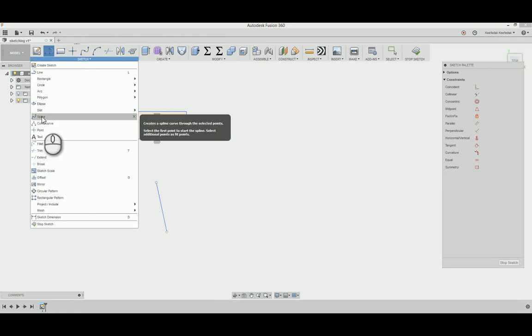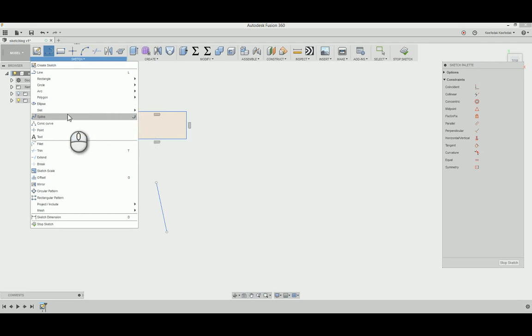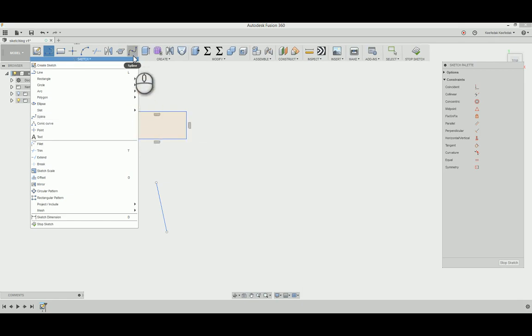Now, I'm going to just show you since we're here. I just exit. Notice spline on the very right, it has this up arrow. That means if you click that, it will pin it to the top toolbar. So you can click that up arrow and it will pin up to the top here. My advice on best practice, only pin things that you can't quickly get from the keyboard. So don't pin line. Don't pin circle, like the center point circle, or rectangle, because those you can hit on the keyboard, okay? Just pin things that don't have a keyboard hotkey, okay?